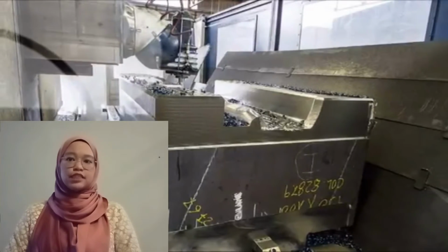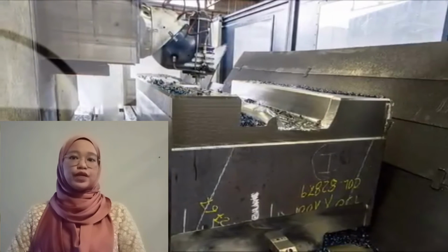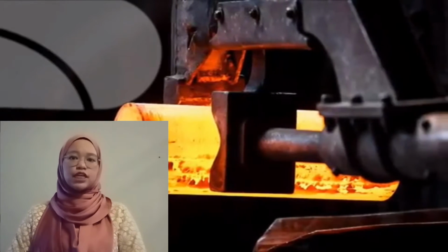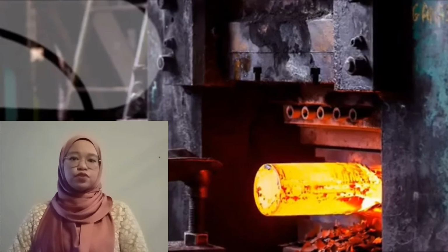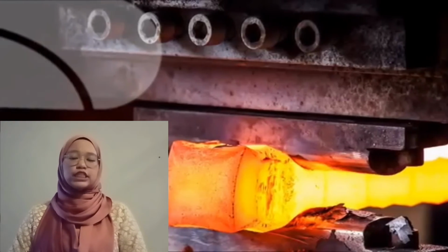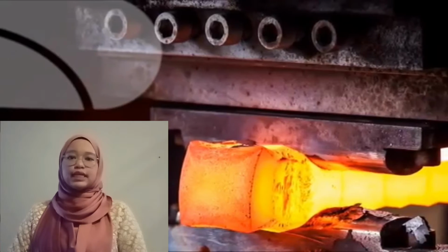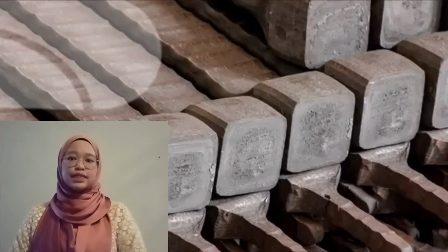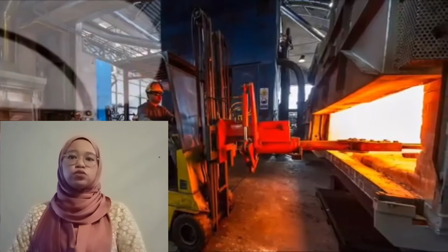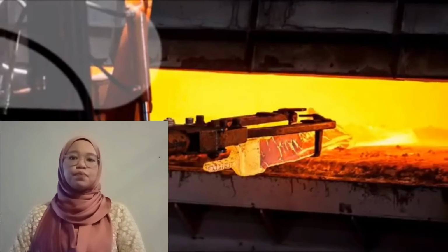The fabrication process of the nickel alloy as a turbine blade in aerospace application is forming and casting operation. For forming fabrication, the technique used is forging. Forging is mechanically working or deforming a single piece of a normally hot metal. Forging is divided into two, namely closed die and open die.